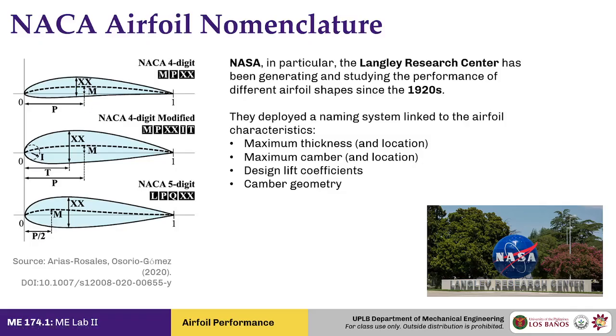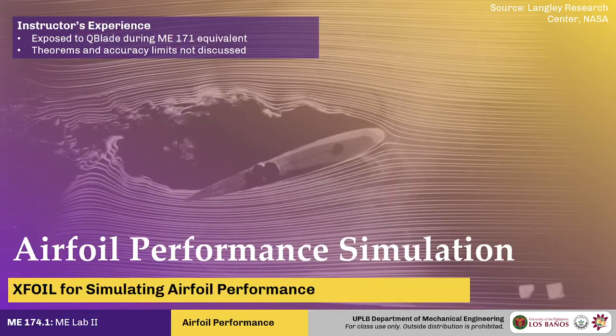So there are more advanced NACA terminologies, like for example, the NACA 5-digit naming scheme actually includes the design lift, or the design maximum lift of this airplane. So we will not tackle that, but you can be free to explore how they actually decided on what the design lift is and how that influences the geometry of the airfoil. But we'll leave that for later for you to explore on your own.